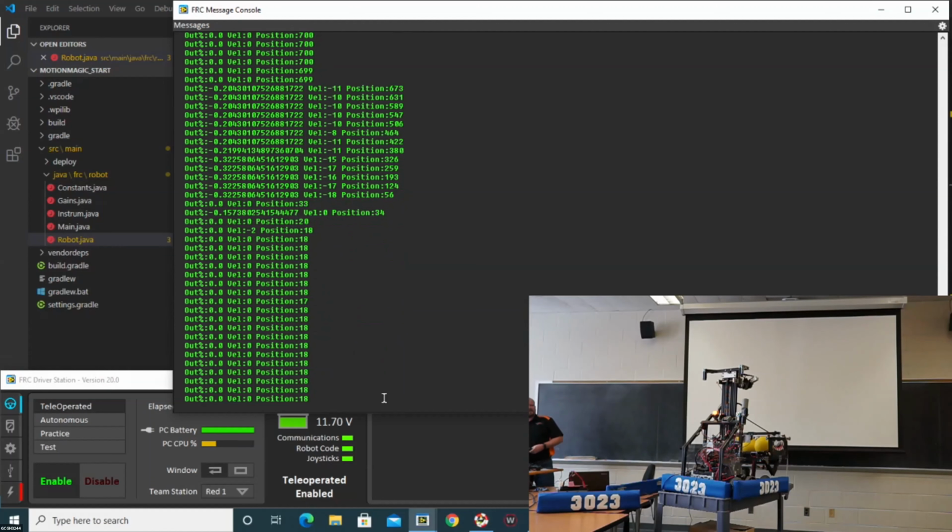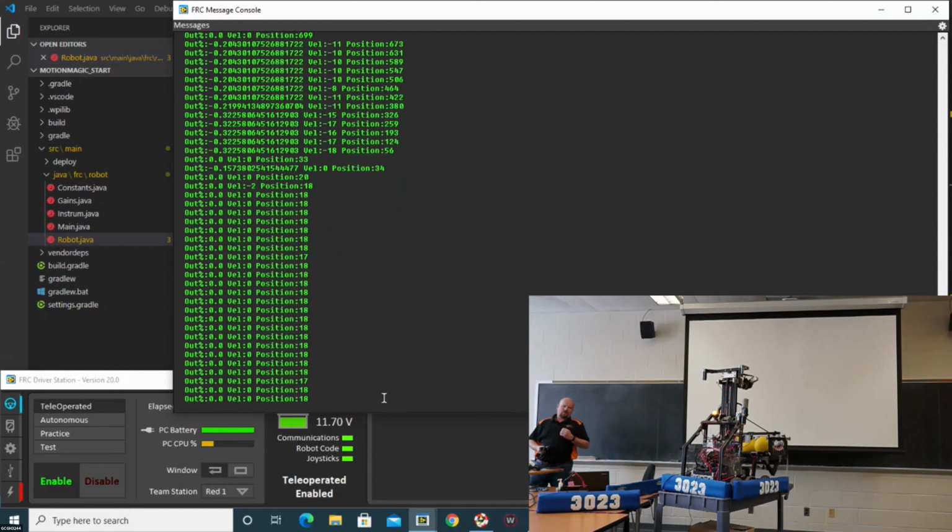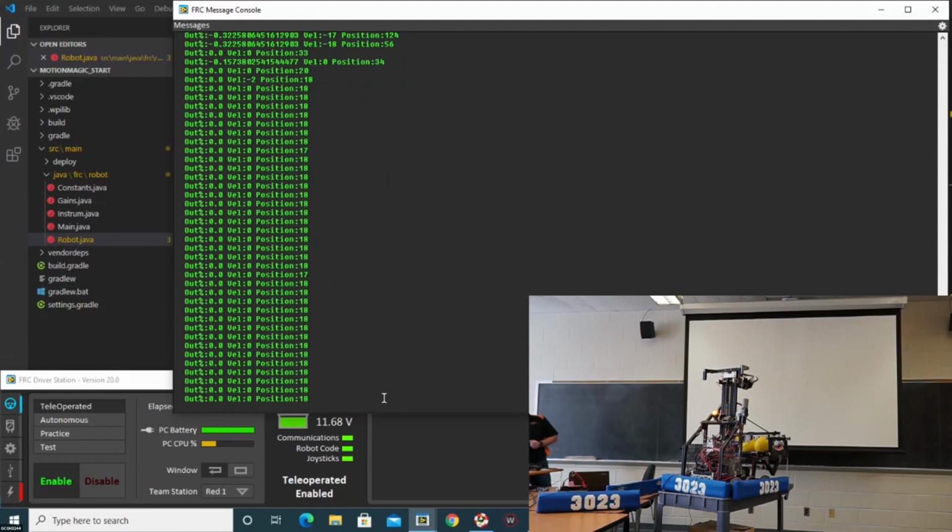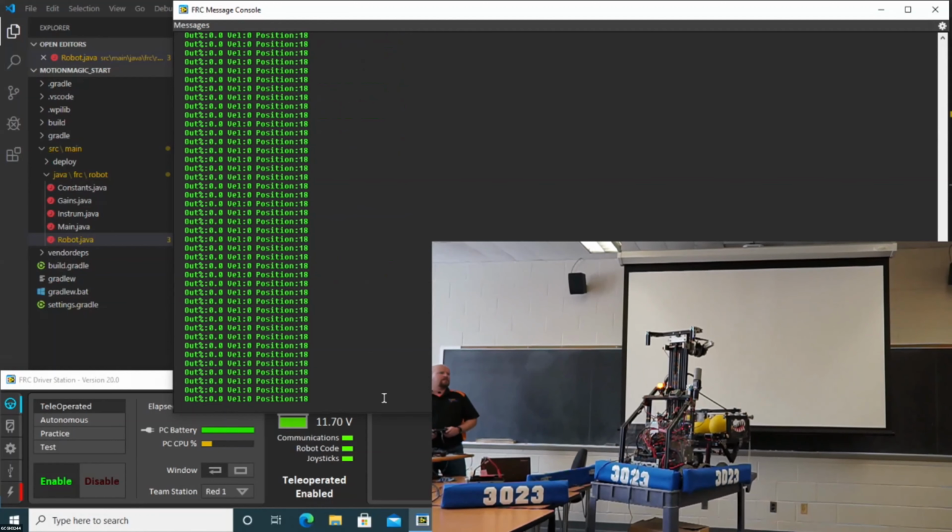If you're on a mechanism like this that has hard stops, you're going to have to go max speed on the joysticks, but let go before you actually crash. That's why I recommend doing this the first time on a drivetrain, because you can continue to run that drivetrain forever without crashing as long as you have the robot blocked up. So I'm going to hold down the joystick and go full speed till I get about half or 3/4 of the way up.